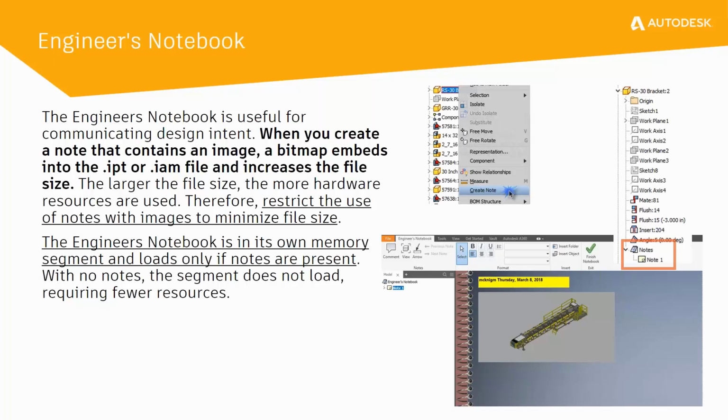Now, if you are using this, try to restrict the use of notes, whilst at the same time minimizing the size of the images, or potentially even not using images at all. The reality is, by putting a lot of images into this, screenshots, screen dumps, or research information, this again increases the file size and potentially affects the way that the file works when opening and using large assemblies.